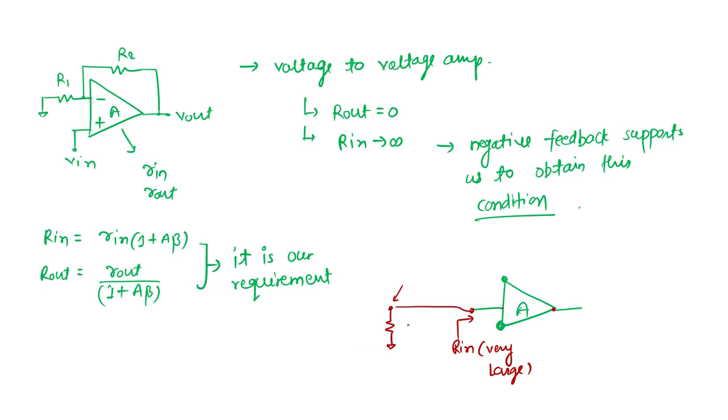That is only possible when there is some circuit or element on the back side of this resistor, and there should not be any loading. If there is loading, then the node voltage that the input of my amplifier is sensing is not exactly what we want here.